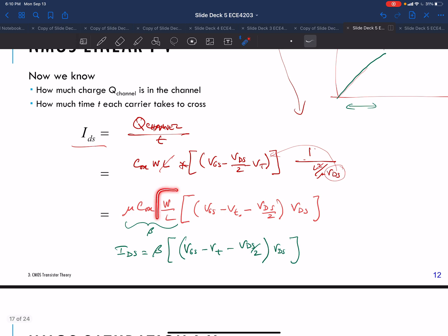Then the higher the capacitance of the gate, the more control you have over the channel. And this mobility is really the mobility of electrons, so it's mu sub n. These two are really for a given process. But as your oxide thickness gets thinner and smaller, the higher your current goes. So as your processes shrink, you can also put more current across the channel.